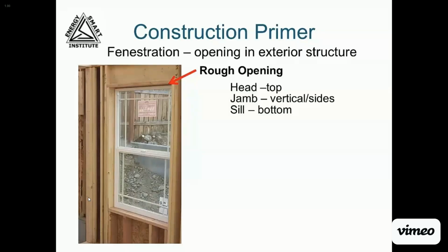When homeowners feel drafts near their doors and windows, this rough opening area is a likely culprit. Non-expanding foam or a foam backer rod can provide a very good air seal and insulation for this envelope hole. Or caulk may be used for the air barrier and then insulation for the thermal barrier.